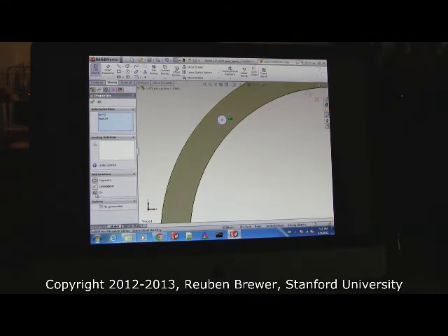See Fix? Fix is bad. You will never have an excuse to use Fix in SolidWorks ever in a million years. This will result in $1,000 robots that don't work. What happens when you hit Fix, SolidWorks says, until you hit that button again, it's just going to keep that hole no matter what. And it does weird things, unexpected, non-linear things. And the problem is, if you do other things after that fix, and then later you unfix it, it retroactively changes everything. So say that you made one part in an assembly based on another, and you sent that part out to get machined, and it was $4,000, and it comes back, and then you unclick fix, and it changes everything, and you're like, holy crap, what happened? It's because you hit fix. Never, ever, ever use fix.